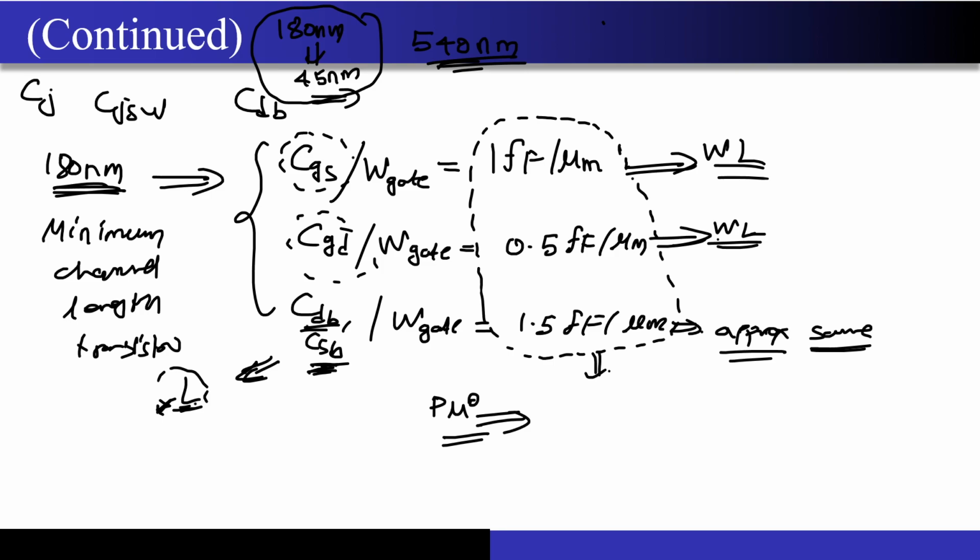The separation between the parasitic second pole in the OTA and the UGB matters. Ideally, if you make it 10x separation between the omega UGB and the omega pole of the OTA, that is going to be good, because at 10x frequency the contribution will be almost negligible.